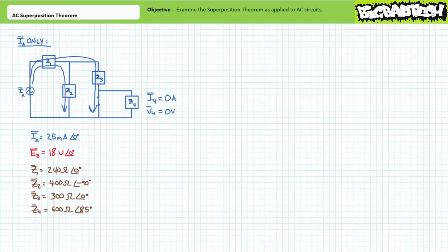Note that any current traveling out of impedance element Z3 will travel through the zero impedance short rather than the path afforded by impedance element Z4. The inclusion of the short has effectively removed impedance element Z4 from consideration. No current will travel through impedance element Z4, and there will be no voltage drop across it. I4 equals 0 and V4 equals 0.